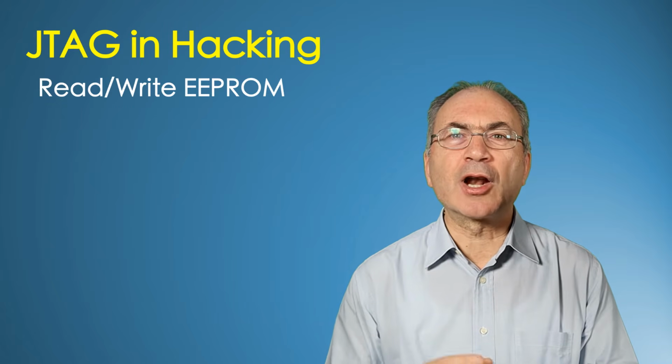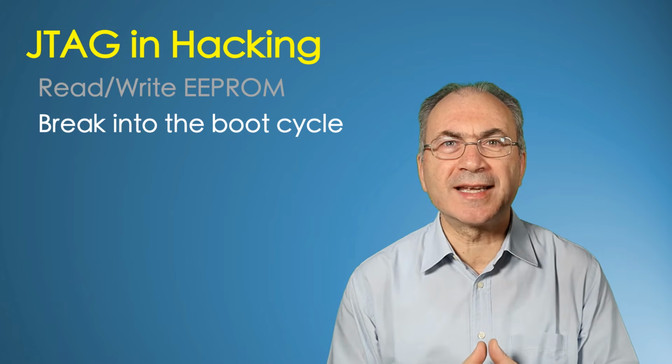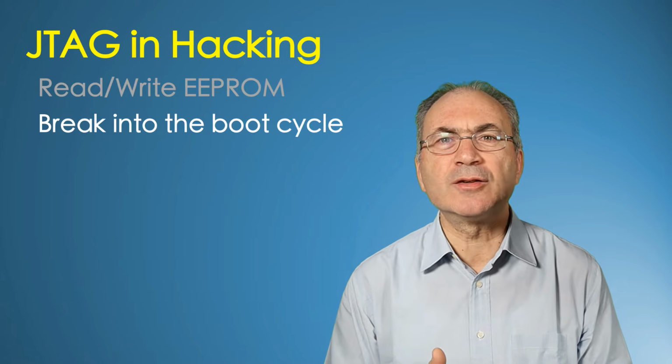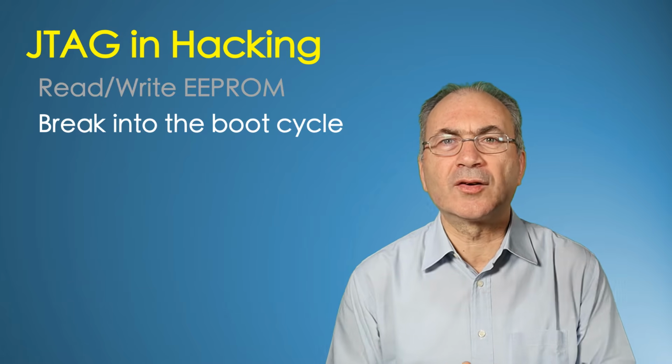It also allows us to break into the boot cycle and to use the JTAG interface as a means to do in-circuit debugging. This means using a debugger, like for example the GNU debugger, with the real firmware over the real hardware.